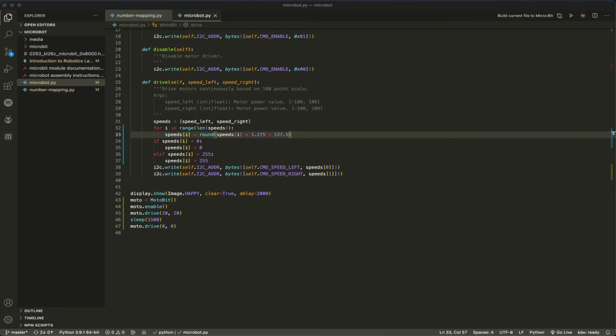The reason for the robot turning clockwise instead of straight is the motors are sort of flipped. You can imagine the left one was going the correct direction, which would explain the clockwise direction, with the left one going forward and the right one going back. It's just because the motors are flipped once you assemble it.